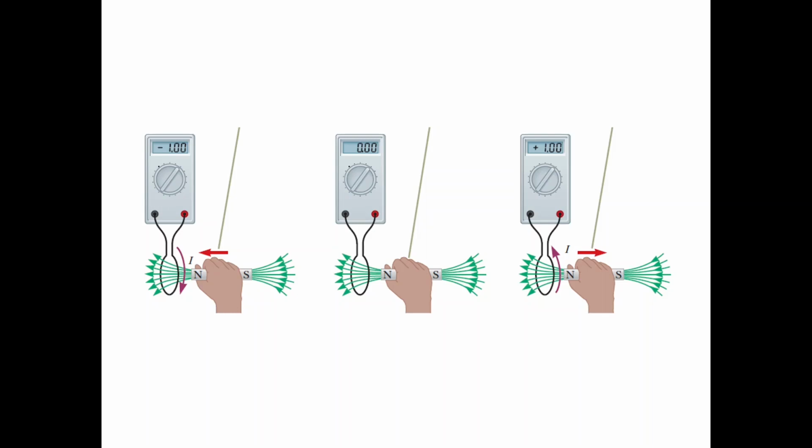However, let's say our circuit is just this loop. So there are two terminals. You cannot connect in different ways. So you will connect it always like this, no matter whether you connect an ampere meter or a voltmeter. So what is inside this device that is different and defines the possibility to measure current and voltage? It's resistance. Internal resistance, exactly.